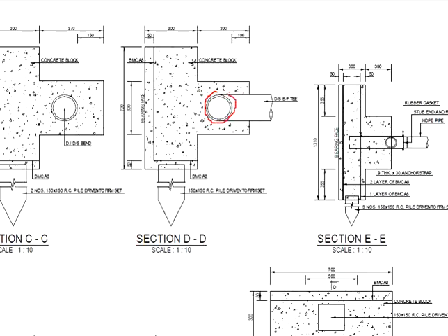This is the water main 150 passing through the concrete block, and then you have a T-joint here creating an additional outlet of 100 mm diameter that is later to be connected with a sluice valve and then a tapered fitting before entering with the joint for the 63 mm diameter HDPE pipe. This is the reinforcement bar, and the dimensions are given here.